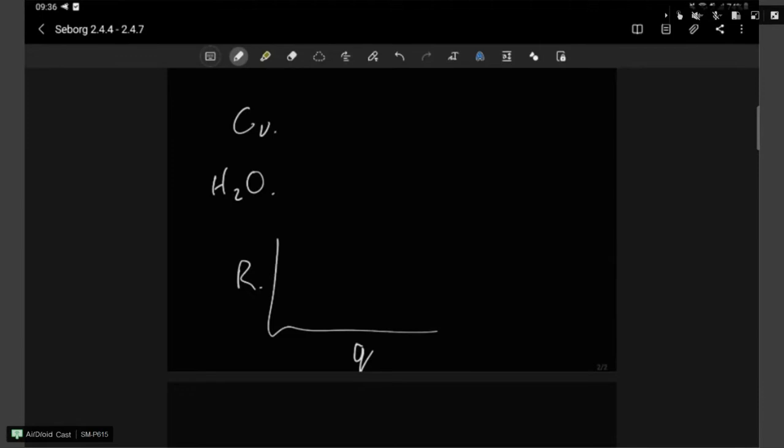So CV is not the resistance. The resistance is the one that's usually below the line. So it's actually kind of an inverse, but it's not 100% the resistance only. So I don't want to put CV here, but let's call it something else. It is some form of a characteristic of that valve, which it imparts on the fluid flowing through it, and that causes that delta P, the pressure drop through the system.